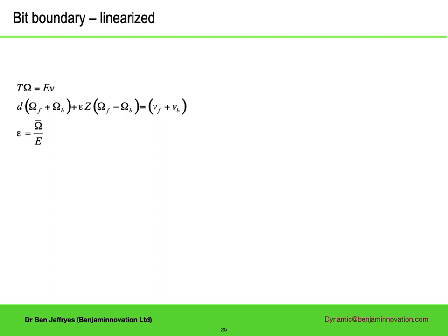One of the equations is nonlinear. Let's look at what happens when the system is in steady state and there is a small disturbance. So I am linearizing around a steady condition with a mean rotation speed and a mean depth of cut. Not the depth of cut per revolution, but the depth of cut per radian. There is one term multiplying the rotation speed. Remember, this is the small varying rotation speed on top of a mean term, and another multiplying the torque.